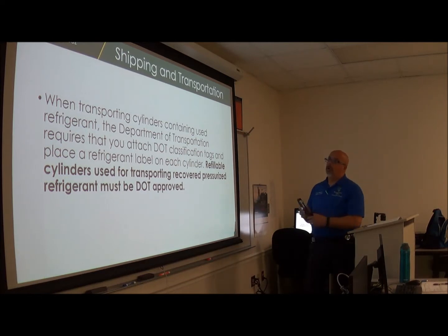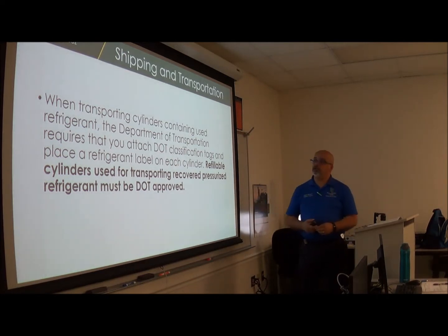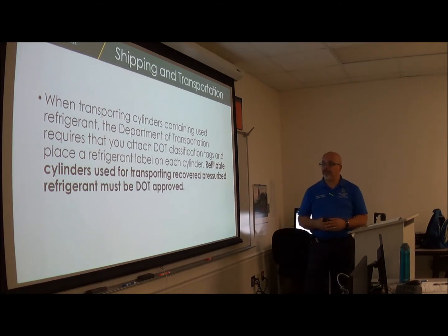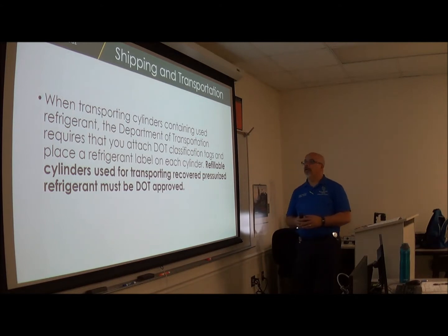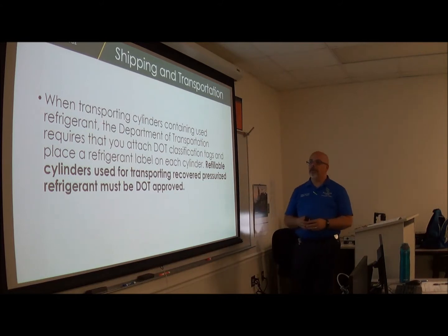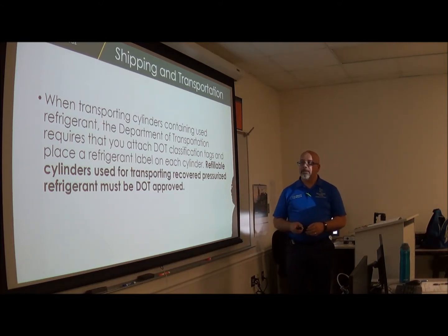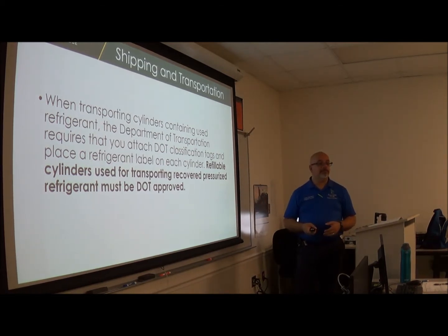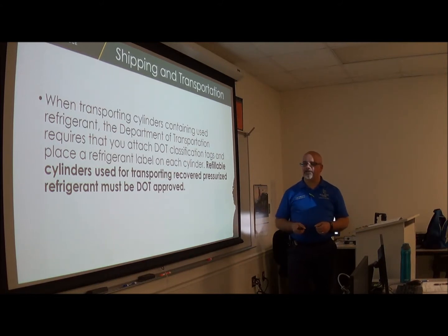Okay. When transporting cylinders containing used refrigerant, the Department of Transportation requires that you attach DOT classification tags and place a refrigerant label on each cylinder. Refillable cylinders used for transporting recovered pressurized refrigerant must be DOT approved. These vehicles also are the ones that we see in the street that have the warning signs around, because this can be highly flammable. Correct. Little placards on the back of the truck often say hazard material. Okay.